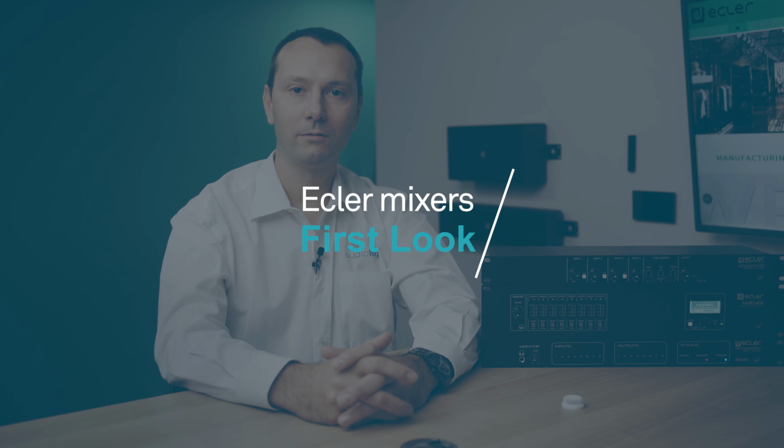This week we're going to take a look at the Ecler mixers and matrix ranges and the applications that they fit into. First off, let's take a look at the purpose of a mixer. As the name would suggest, a mixer combines multiple different inputs and can mix them together to either one or multiple outputs. Mixers often form the center of modern audio systems, as we are often dealing with multiple inputs such as microphones and program material, as well as multiple outputs such as speakers and recorders.